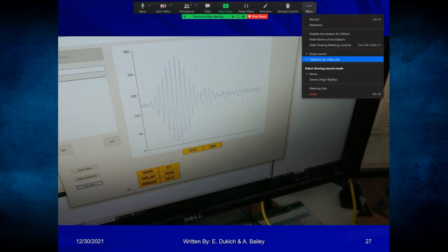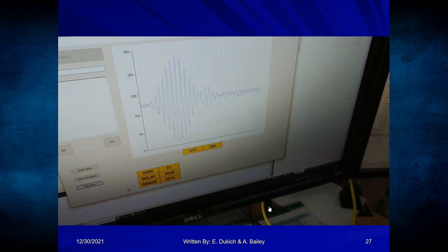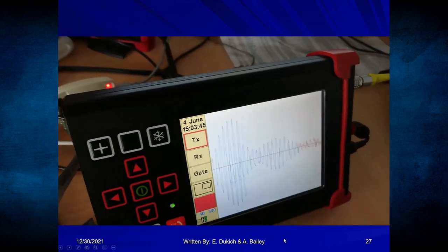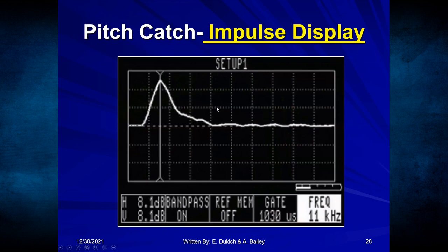I have another one that's actually a live video, and it's coming up in just one moment. That was one type, called an RF signal. That RF signal showed me the top and the bottom, or small, medium, large signals. But this impulse technique is actually pretty sensitive. We're going to see a quick video of the signal changing from the top of the screen to the bottom of the screen. If the flaws are bigger, we're going to have a larger size signal.